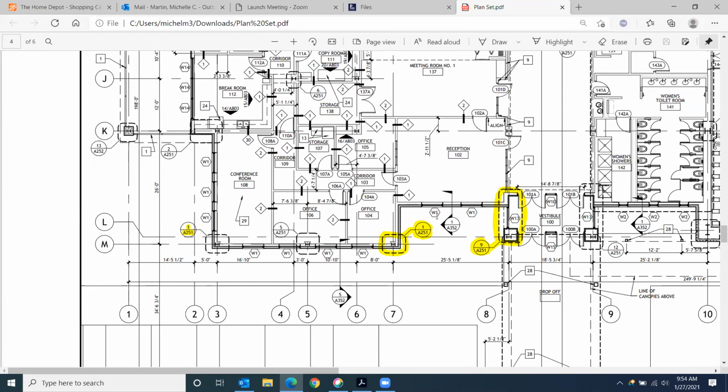But with this overall floor plan, and we refer down to some of these little detail views, you can see that this detail of this wall section is going to be located on page A251, and it's going to be drawing 1. Here's another one. It's still drawing 1, A251. So even though these are in different locations, the way these wall types and wall joints are created are similar. So the contractor can see that. Also on page A251 is the detail of this wall section right here, and that'll be drawing number 9.